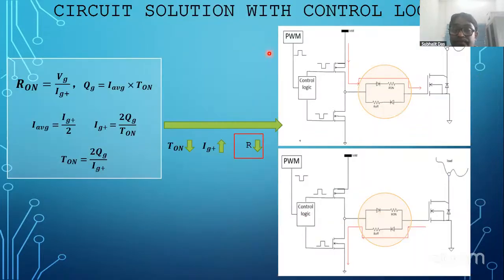So what can we do? We can do something so that the MOSFET takes less time to switch on and off. Another thing: whenever heat starts generating, we can control the speed of the gate driver, making it a little slower, that is the pulse width we give the MOSFET for switching on and off. We try to stop the MOSFET for a while so that it gets some time to dissipate heat, and we continue this operation until the heat becomes lower. So this is the corresponding solution.